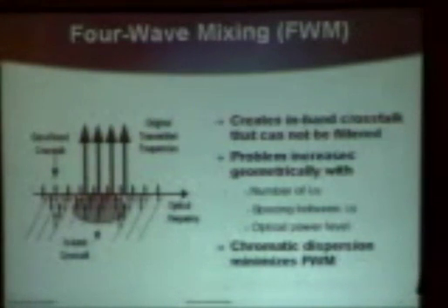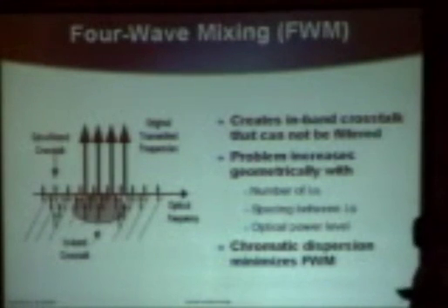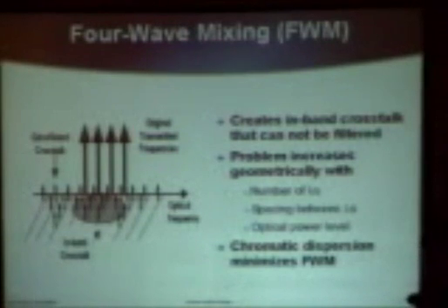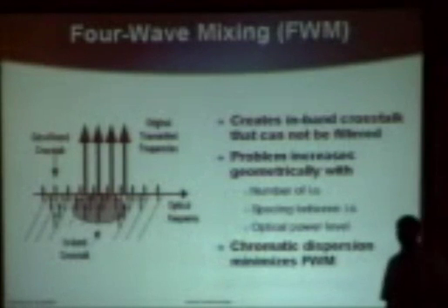And if there's not enough problems, just to show you some more, along comes WDM, which we're going to talk about in a minute. The issue with WDM was, if there's no dispersion between the wavelengths, as in this case the four primary wavelengths travel down the fiber, they tend to interact with each other, and they create all these different beat signals. Think of it in terms of radios. It's the same thing.